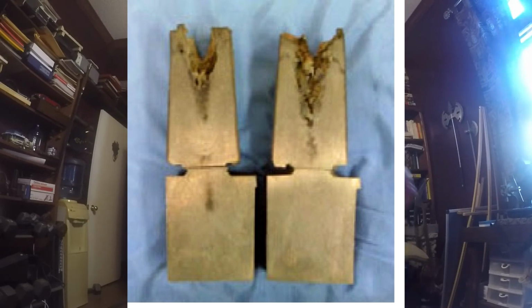If they were able to zoom in on that, they would see they cut into a portion that didn't solidify, or rather didn't get fed by the riser and solidify before that neck choked off the metal and froze.